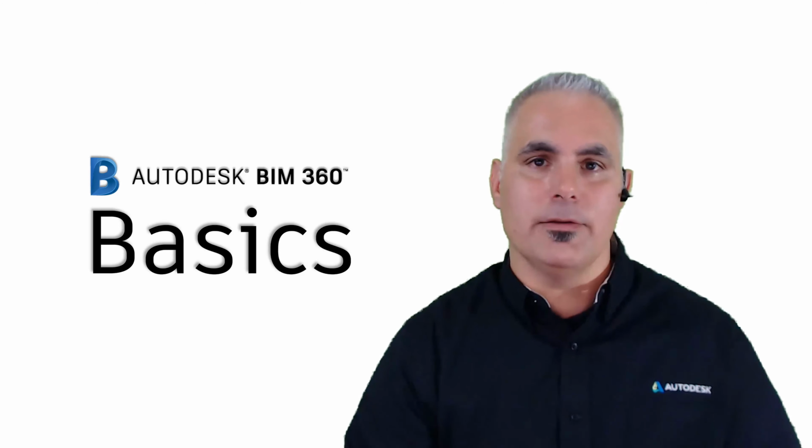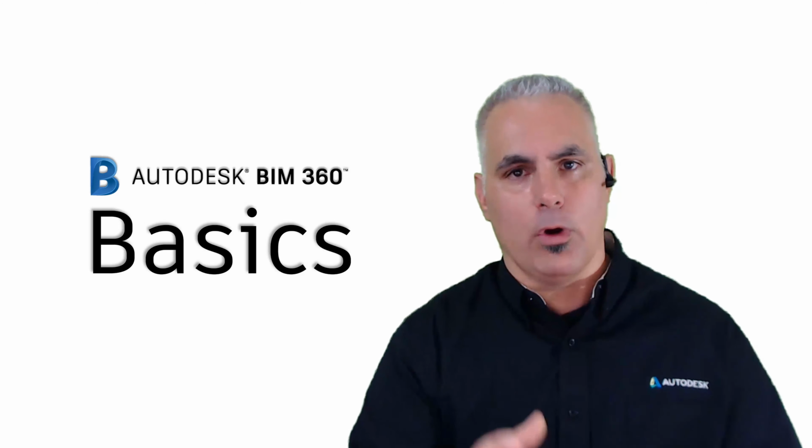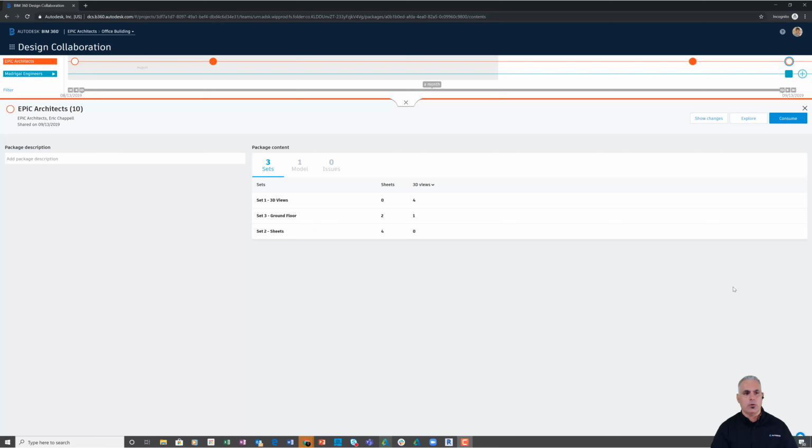We've been talking about different ways of sharing and collaborating using BIM 360 Design. And we're on the last one, and that's consuming packages. So right now I'm logged in as Tom Anderson, and if you remember, he's the structural engineer on the Madrigal Engineers team. While I'm in BIM 360 Design, I can see the timelines of other teams, and I can see the Epic Architects timeline. And here at the right end, I see the package that was created by the Epic Architects team that I showed you in the last video.